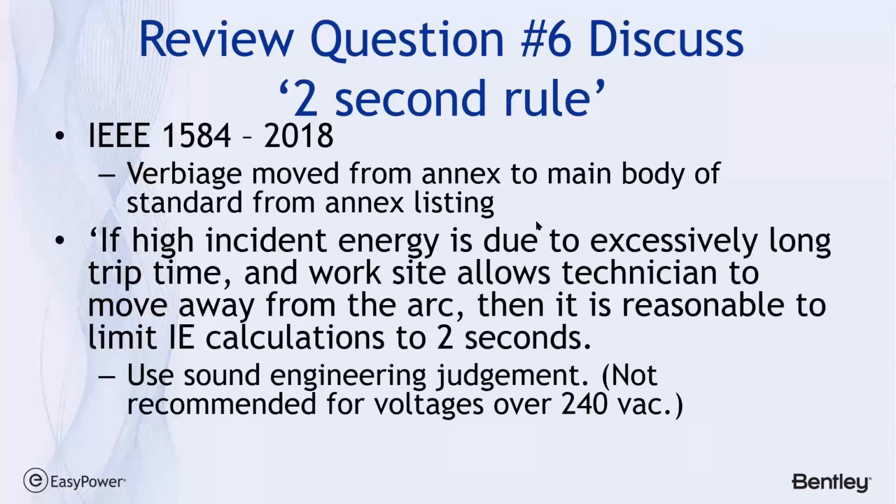So it would really strain my grits to sit there and apply a 2-second limit on any voltage, unless I knew for sure that we had coordination in line. So no, maximum time according to the standard is 2 seconds on any voltage. And I hesitate to go anything beyond that.